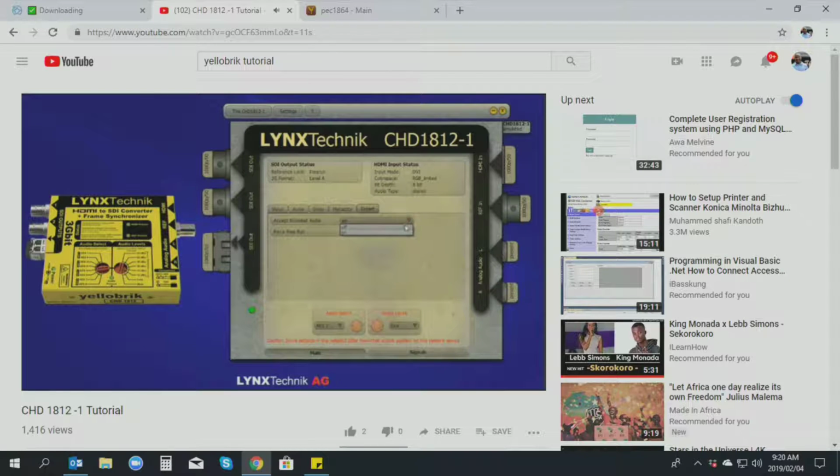If you switch this to off, what happens is EDID answers back to the sending device, no, I can't process AC3, Dolby Digital, or any encoded audio format. Only send me PCM. Then the sending device will send PCM audio, and then that'll be embedded as PCM audio in the output. So this is basically an on-off switch for accepting or not accepting encoded audio.